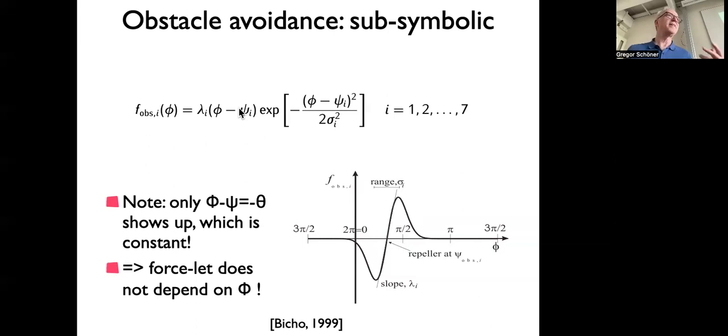We had people who did lab classes with us who didn't believe that. We just showed them that you can turn off that sensor and it doesn't change the robot behavior, right? The front sensor does not contribute to obstacle avoidance. It's essentially neutral with respect to going around it on the right or on the left, right? It's forced to 0. We had that front sensor because we also controlled the speed of the robot. And for that, the front sensor was the most important one. And the chapter that you study has some explanation of that, even though you don't need to study that in detail.